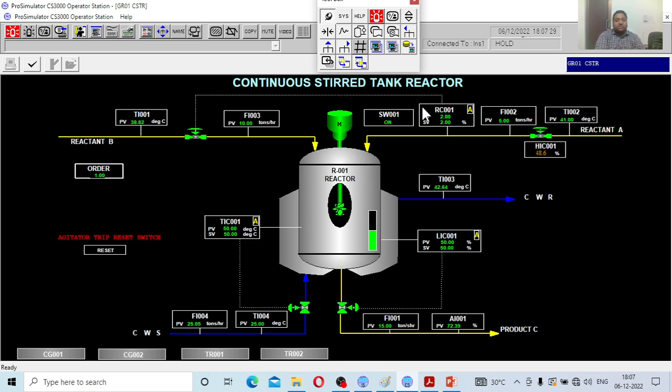So the job of a ratio control is to change the valve position of B so that the ratio is 2. B to A should be 2. Accordingly, you can see if you pump more material into the reactor, the process value presently will drop down because more is coming into the reactor. If more is coming inside the reactor, automatically the temperature will drop.